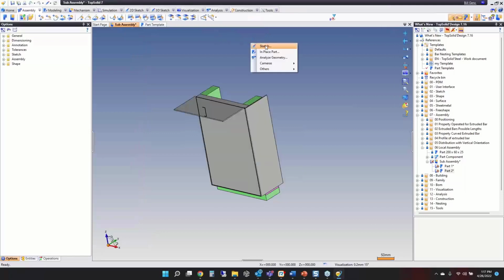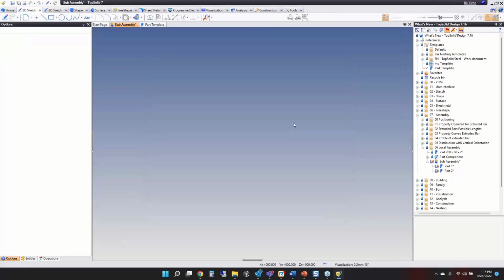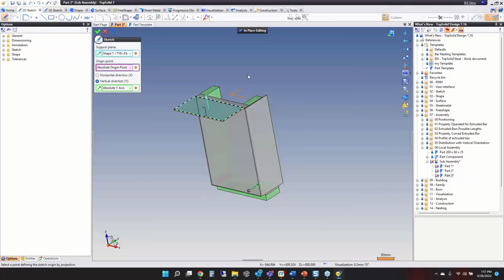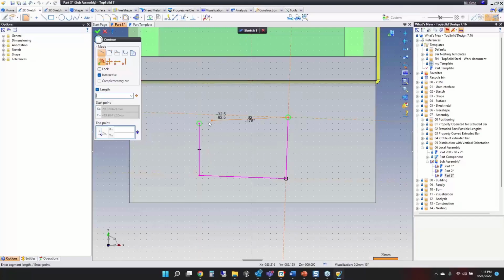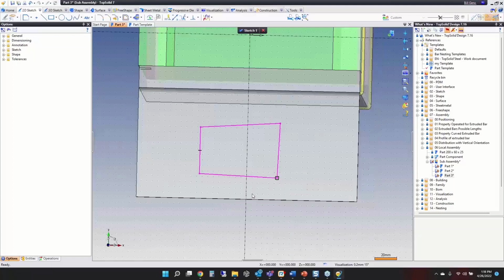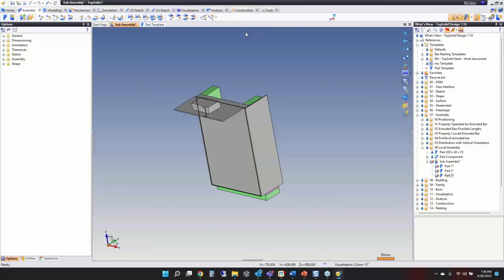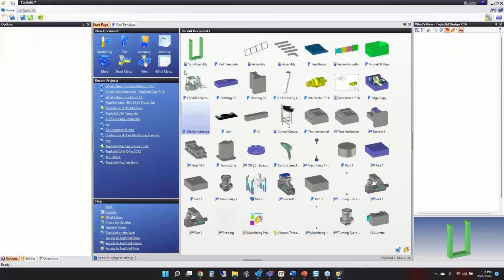And then if I just create a sketch for an in-place part in space, right? Now it's going to ask me for a sketch plane because it's going to go straight into my contour command, and boom. So again, the idea is you can just capture some of the more basic things you do with an in-place part and really control what command is launched to help get you started with that new design. Okay? So we're going to make a widget there. Extrude the widget. We now have a new part, and we made our 3 new parts nice and quick and efficient. Cool. All right, let's go ahead and close that stuff down.